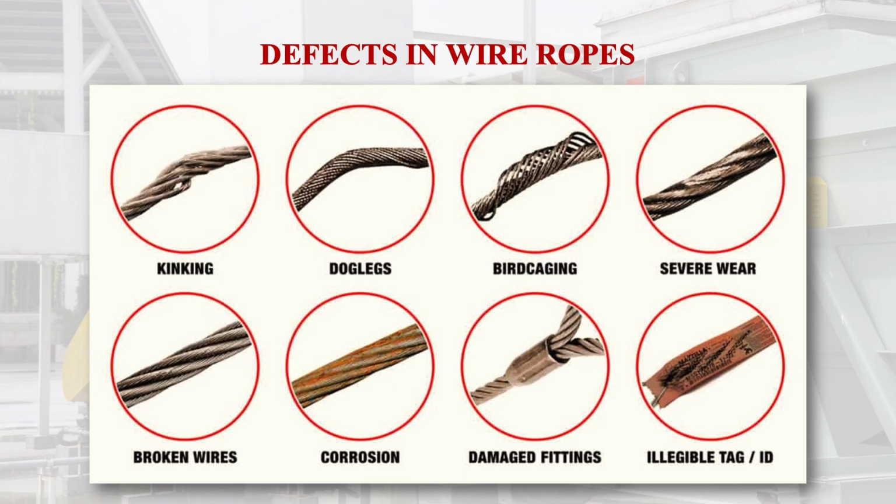There are other portions which should also be checked for smooth operation of the crane. Some items are beams, where there should not be any obstructions, and trolley movement, bearings, motor, and shafts. All these items are checked as a part of preventive maintenance.